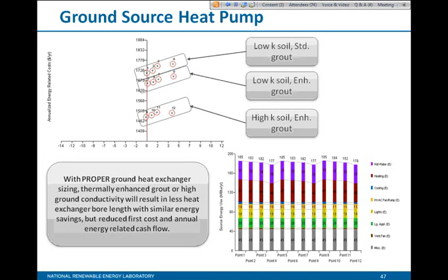In DOE-2, the default modeling, when it goes to two-stage, pretty much takes one performance curve across the entire operating range, and it also takes the total capacity instead of the sensible capacity.